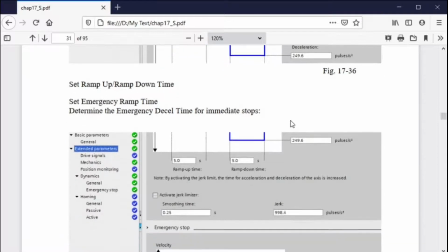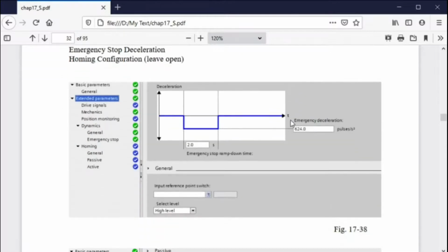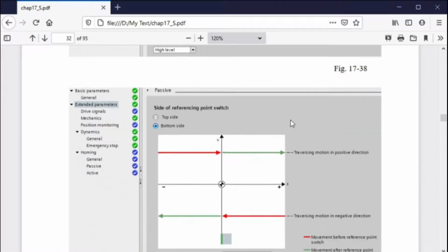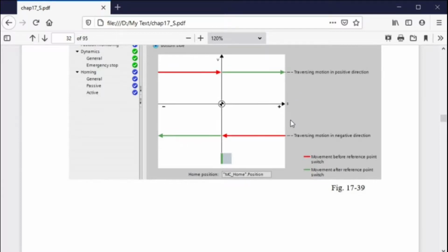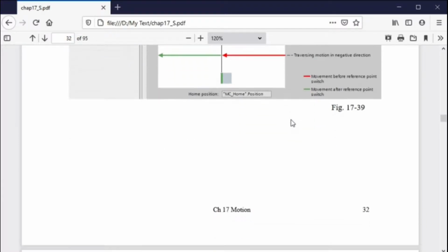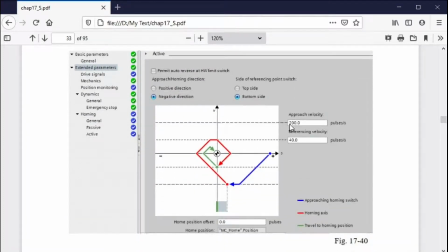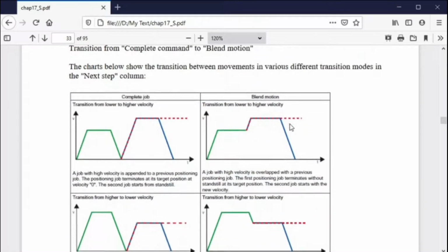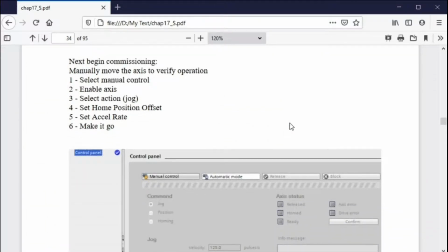For the Allen Bradley servo, I think it's 200, so you need those numbers when you say move. If I want to move 200 in Allen Bradley, it would go 1 time around. If you say move 400, it would go 2 times around. If you say move to 0, if it's an absolute move, it would be back to home or back to 0. So again, that's information that you need, and that's pivotal in being able to program your application. So those are the only 2 actual things you need.